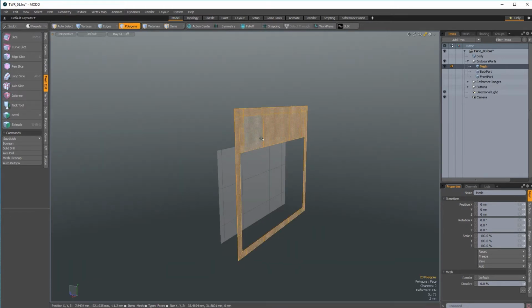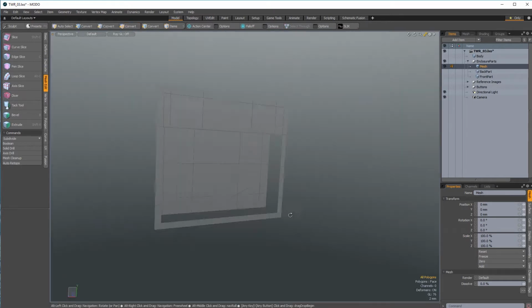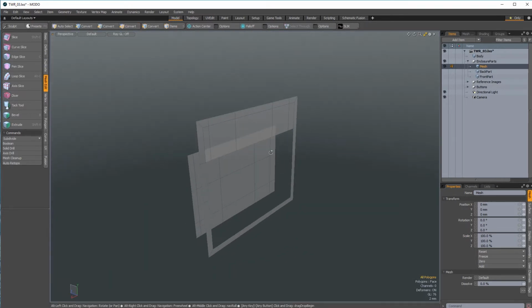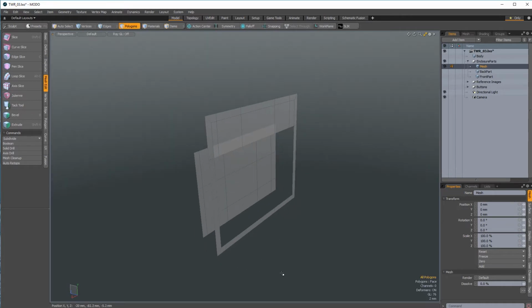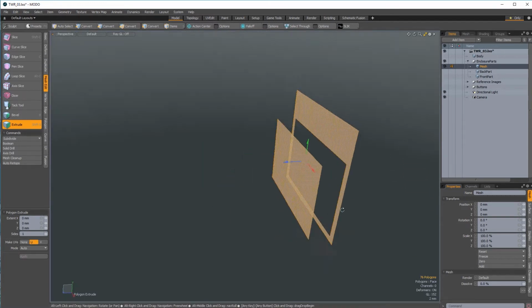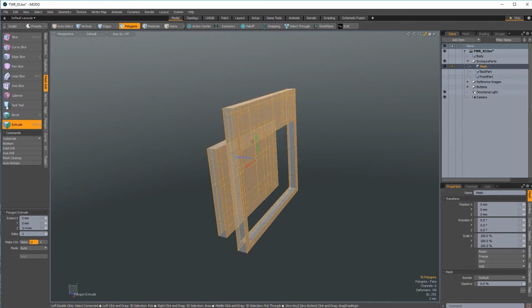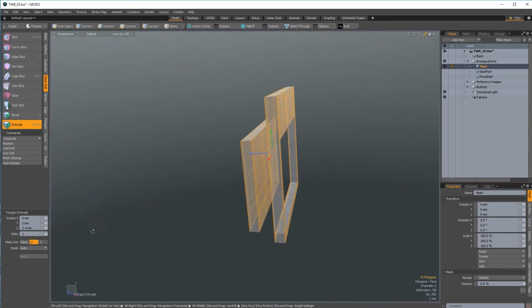I'm just going to scale these to 0. I know they're flat, but I just like to double check these sorts of things. That looks good. All right, so let's grab these polygons and we're going to hit Shift X for the Extrude tool. And I'll just click in the viewport just to show you how it works. This allows you to extrude along a single axis in any direction, like so. So it's a bit limited, but it's also very useful when you do need it for a particular thing.